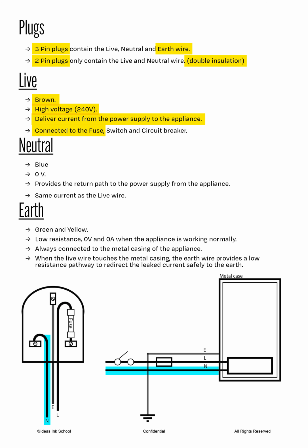Next up is the neutral wire. This wire is also easily spotted as it is connected to the live wire. Both wires must be connected to form a closed circuit. As a result, the current found in the live and neutral wire must be equal. A neutral wire is blue in color and is rated at 0 volts. Because the live wire is rated at 240 volts, this causes the current to flow from the live wire to the neutral wire across the potential difference.